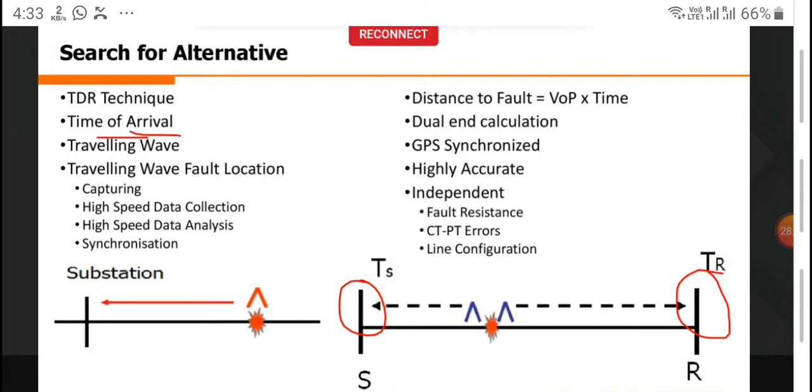Now what exactly happens here is, first of all, whenever the system is there in the line, because we are dealing with the online system, before installing the system, we always have to have a calibration of the line. So you always need to have a calibration of the line done before taking your system into the line. So first of all, what we do, we always calibrate it from both ends, from a breaker that is present here, then the breaker that is present here at the other end of the line.